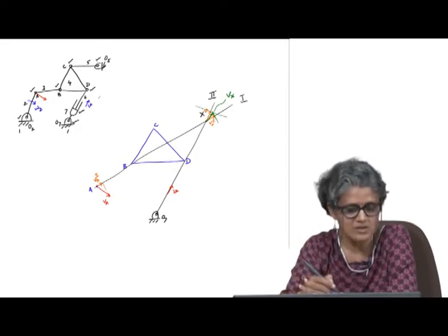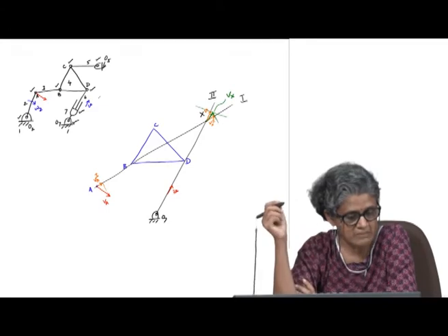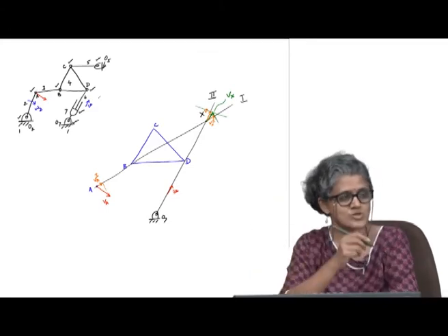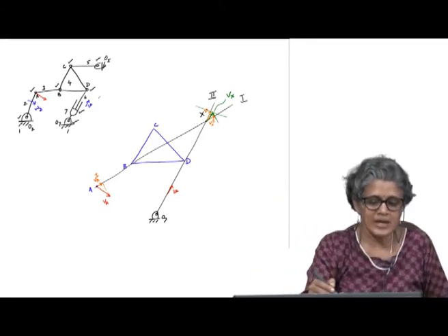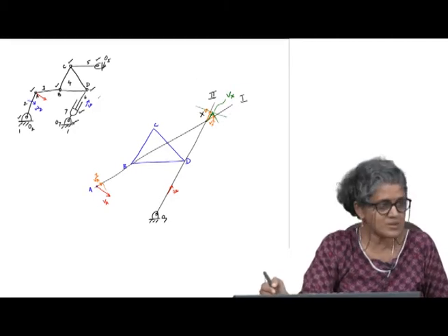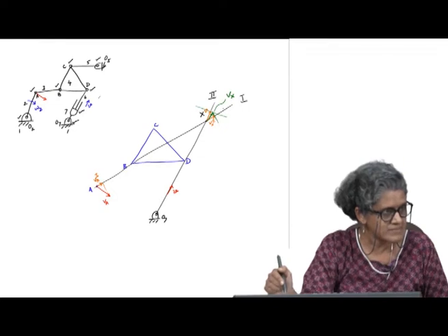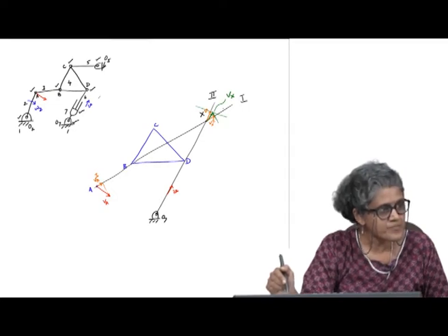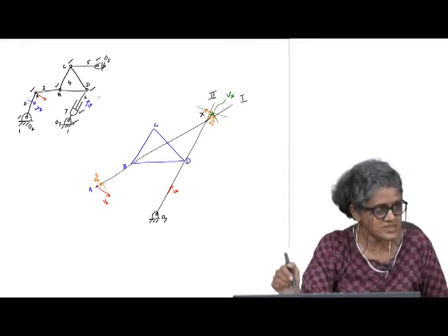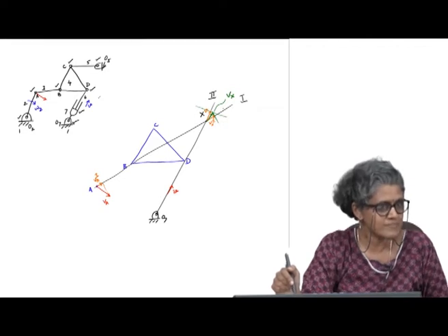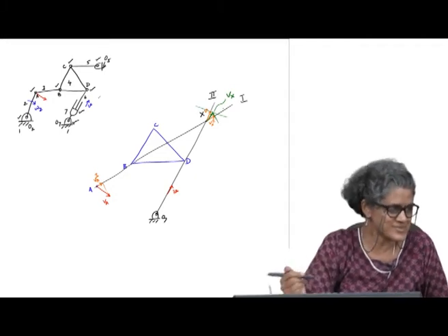In the case of AB, your question is, can I draw the third auxiliary line from O5 to X? You cannot draw it because it is not a motion transfer point. Yes, X is not a motion transfer point. But can we use it? How would you like to use it? If you want to use it, how would you like to use it?